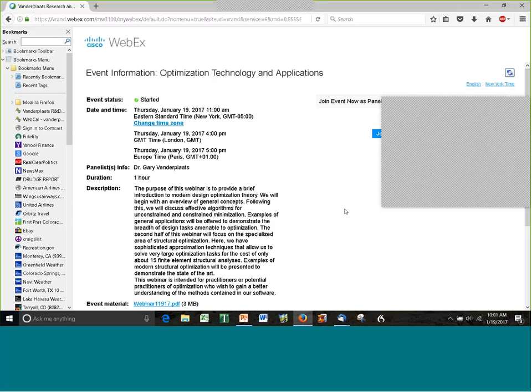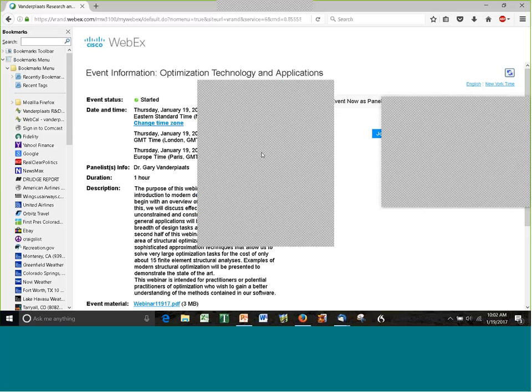The type of manufacturing constraints that are there, the list is pretty extensive. In total, there are about 18 different families of manufacturing constraints. They include castings, mirror symmetries, extrusions, radial extrusions, radial castings, cyclic symmetries, etc. The complete list is up in the documentation, but like I said, there are about 20 different families of fabrication constraints that you can enforce on a given design.